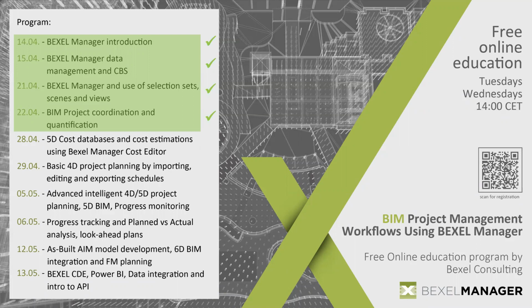And last week we talked about selection sets and element grouping. We mentioned simple animation options and ways how to coordinate a BIM project using clash detection. Also, I briefly explained how to calculate and extract quantities from the BIM project using the quantity takeoff module.